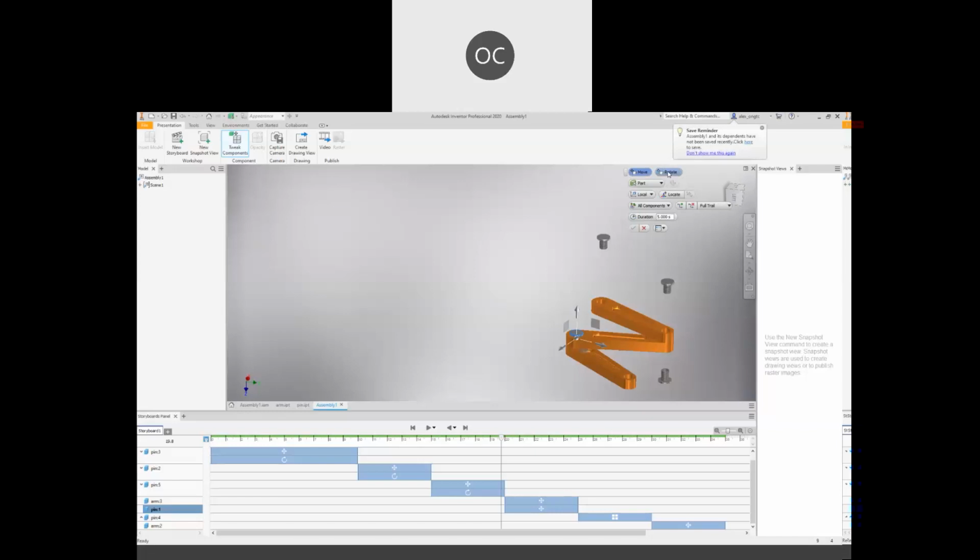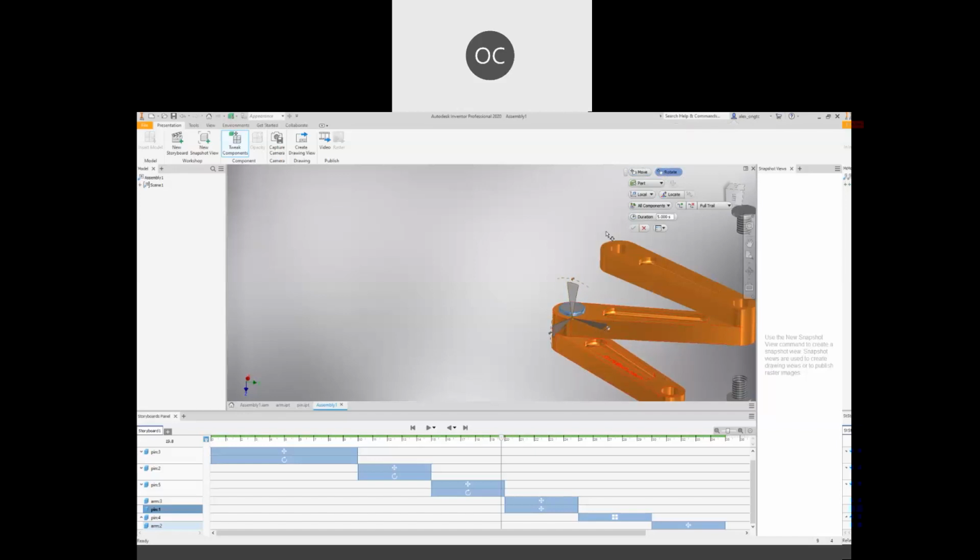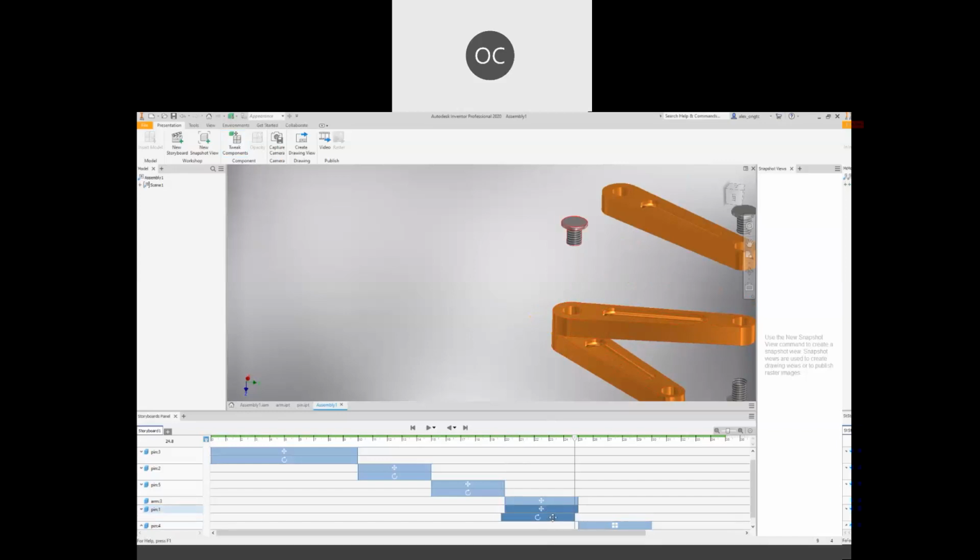So once you click on rotate here, similarly, they will ask for your rotation angle and your duration. So I want to turn to this direction, maybe to 270 degree, you see, 270 degree, yeah. So if you have move, then you have distance here. So duration here, maybe you want to remain 5 seconds, then you just check. So if you double click on this, you will see the rotation. This will be the rotation movement here.